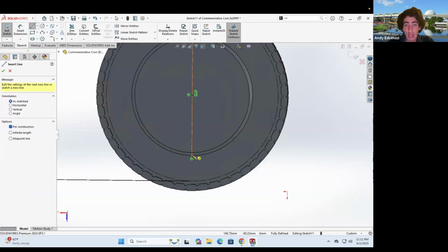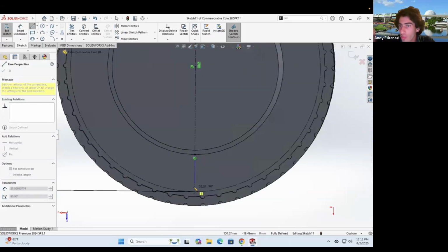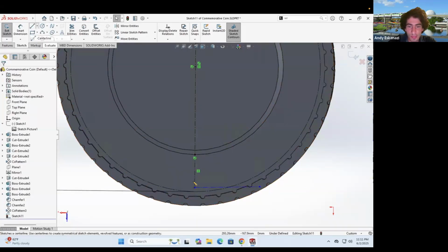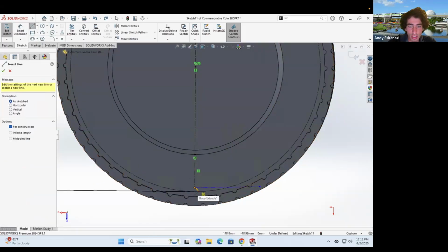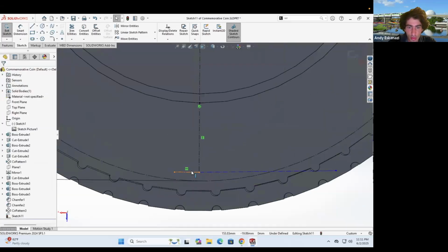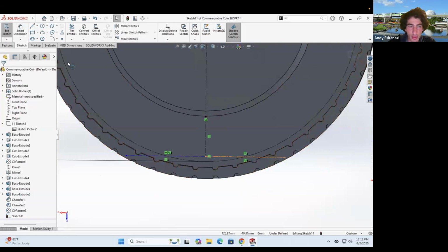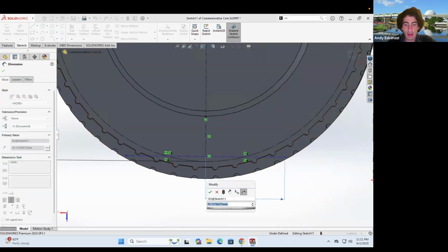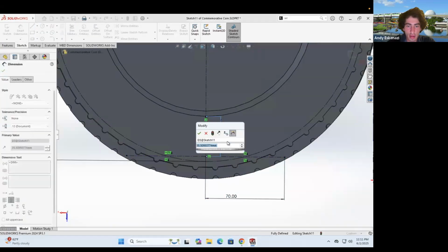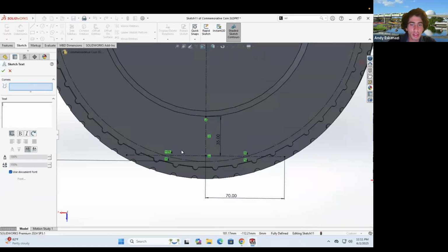What I'm finding just from doing a little brainstorming is that I cannot move around the text as I can do in other software, in particular Siemens NX. So what I'll do is just a little shortcut where I'll write it horizontally instead of curved, on these lines that I'm drawing right now. I'll make sure that these two are parallel and I'll make that perpendicular and I'll make these two equal to each other. And yes, we can maybe leave it like that. 70 is okay. 35.